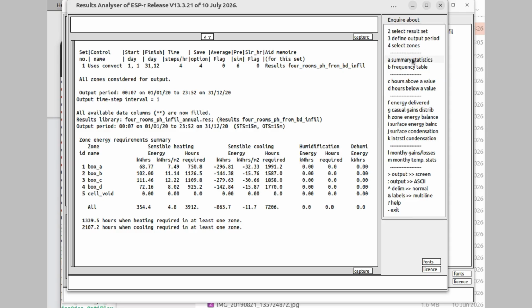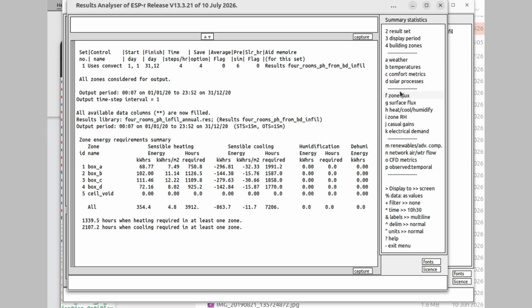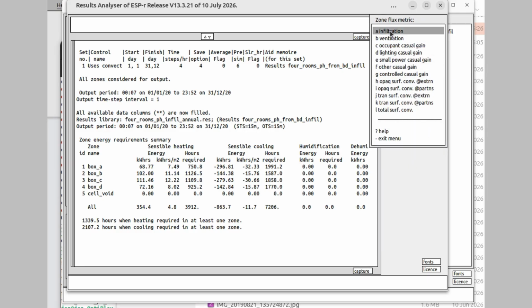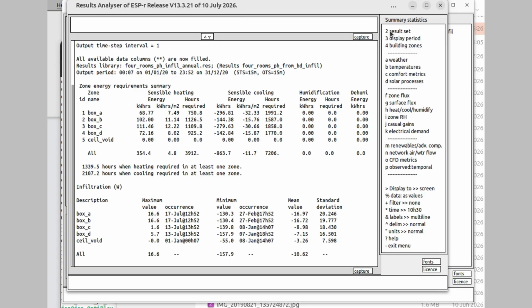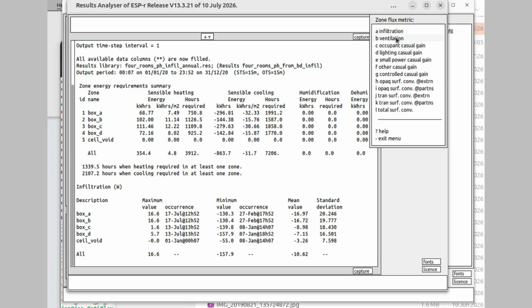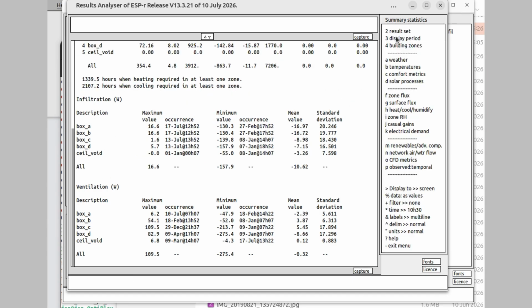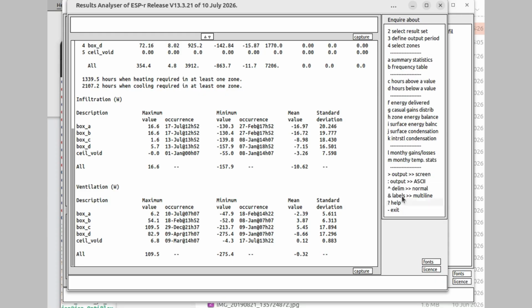If you look at statistics for the energy impact of air movement, we again see that the heat transported in the air moving between rooms can be greater than that implied by air passing through the facade. And this happens even when each of the occupied spaces has been conditioned with the same thermostat settings.